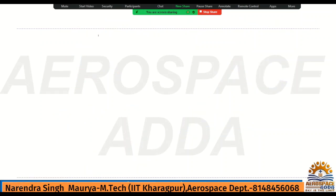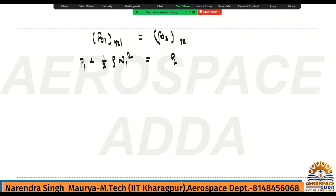Now, P naught 1 relative is equal to P naught 2 relative. The total pressure is the stagnation pressure, which is static pressure plus dynamic pressure. The static pressure at point 1 is P1, plus dynamic pressure. The dynamic pressure formula is half rho V squared. Because it's a rotor, the relative velocity W1 will be there. Similarly, static pressure at point 2 is P2, and the dynamic pressure will be half rho W2 squared, with the relative velocity. I explained earlier why relative velocity is recognized by the rotor; that I had discussed, so now I have written it directly here.